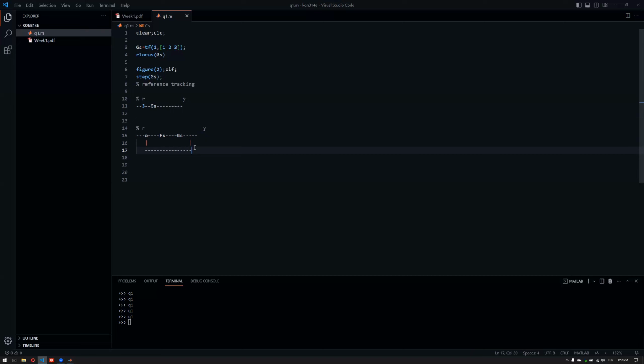For example, if I have a vehicle, it should obey the speed limits. It shouldn't be faster than the speed limit because that will end up in a ticket. So that's something like overshoot, and I don't want overshoot, or I want a reasonable amount of overshoot, like 10%, because that's the law. So that could be a consideration. And then I want, for example, a minimum energy consuming vehicle. So my controller should optimize for energy, or it could be a speeding car, so it should minimize the time, so it should be a time optimal controller.